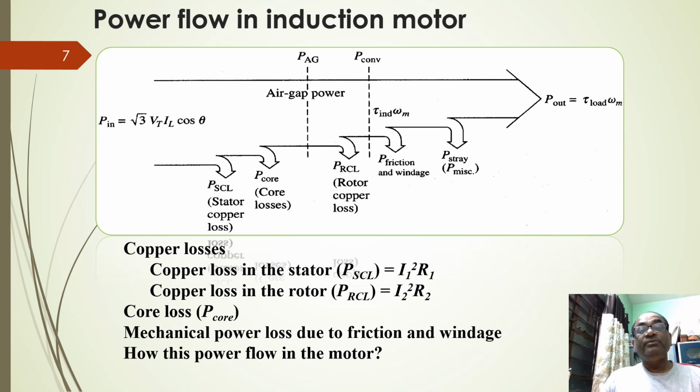So the rest of the power is now available in the air gap and can be taken by the rotor. This is the flux ready to cross the air gap and reach the rotor. Now the rotor winding also has some resistance, and there will be some associated losses, like rotor copper losses, that is I square R loss.